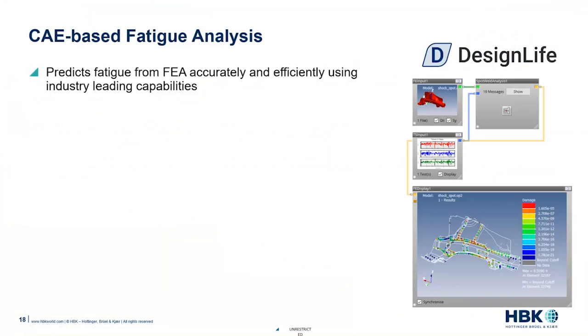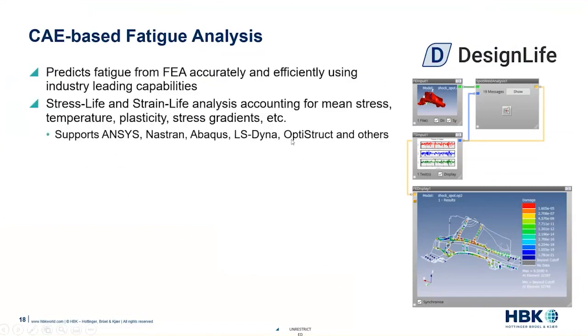nCode DesignLife is a computer-aided engineering tool for fatigue simulation prediction using finite element analysis results from solvers including ANSYS, Nastran, and Abaqus, and others. It includes fatigue damage models for stress life, strain life, and fracture mechanics and crack growth with uniaxial and or multi-axial models.